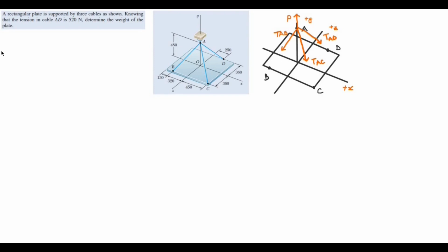Alright, so if you recall from a previous video, tension AB, for example, which is a vector, is equal to its magnitude, which is a scalar, times lambda. And we can simplify this into the magnitude of tension AB times the vector AB over the magnitude AB. So what I want to do is find the vectors for all the tensions first, and then get the magnitudes.